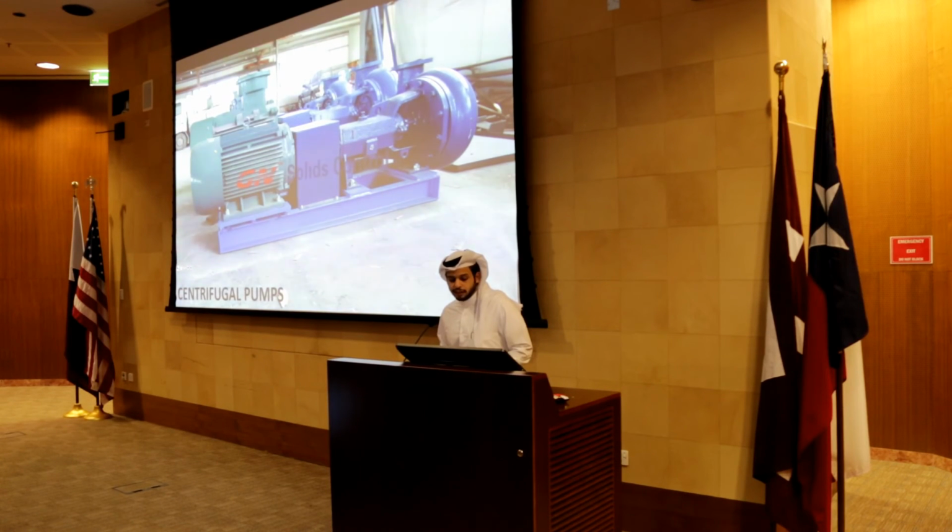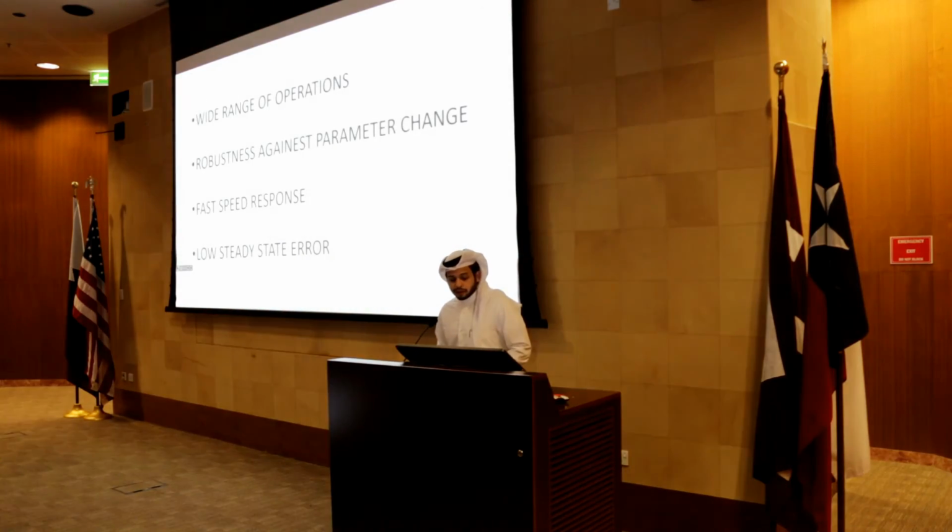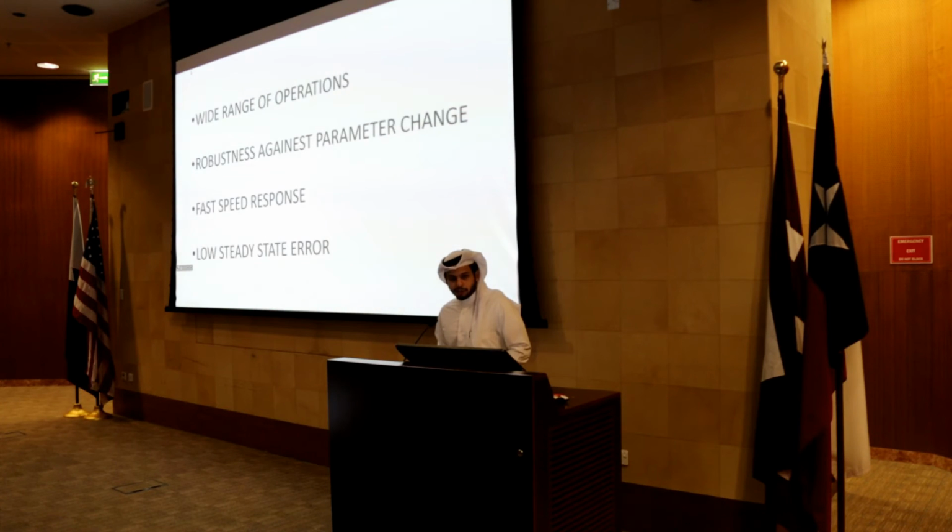Centrifugal pumps are used a lot in the industry as they have very unique properties such as working on a wide range of flow rates. They require the use of variable speed motor drives such as MotorMind to vary the flow rates by varying the speed of the motor driving the pump. The pump requires a minimum safe flow rate, so the motors must be stable and be able to work accurately at lower speeds. What we deduced from studying the applications is the following.